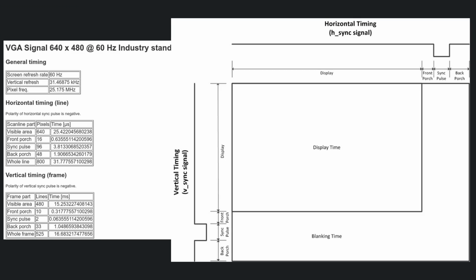Clocks are again another massive discussion, but I really don't want to make this a true clock because those run on special networks on the FPGA, and reading data sources from different clocks requires a bit of care. Also, I don't really have a great way to get this exact clock without setting up a PLL, and I only know how to do that in Vivado, so I'm just hoping that the monitor will be forgiving and accept my 25 MHz clock, which is just 1/4 of my main clock speed.